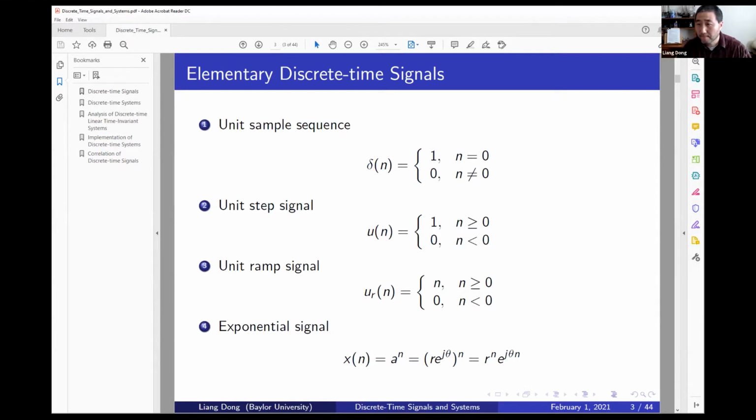So here, we know it's very simple. The signal looks like this. It's just one finite spike of 1 at time equal to 0. This is time n, the delta unit sample sequence. Now we use that when we do sampling. We're actually using a delta train, or whenever we have a delta function on this time stamp, that's the sample we are going to take. What I mean is, if you have delta n minus kTs, where Ts is our sampling period and k is an integer, anytime you multiply this with your original signal, you take a sample.